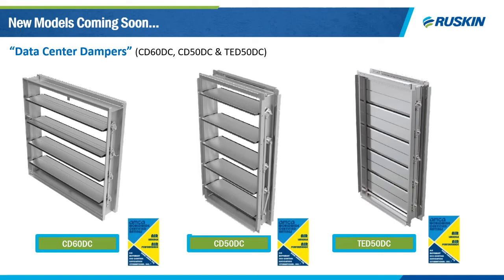So if you're near the ocean, or if you just want to make sure that those blades and frames will last a long time without corroding, the CD50 DC is a great option. And then finally on the right, the TED50 DC is also made of extruded aluminum construction, but this is a little more unique because it has a separate thermal break in between its blades.